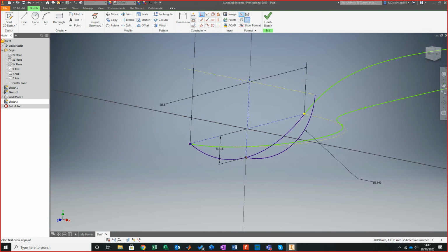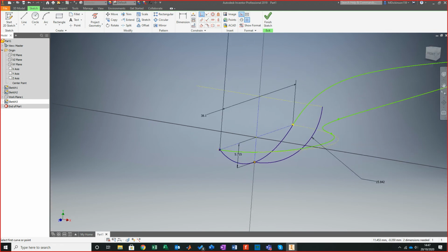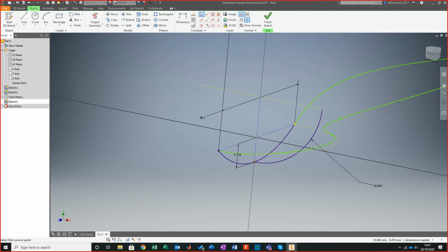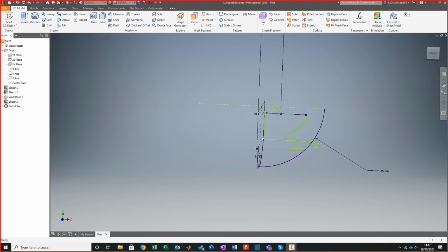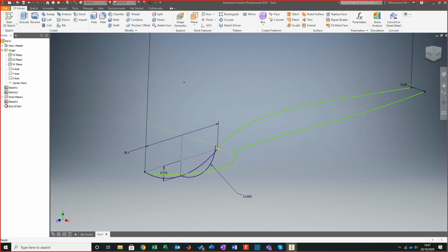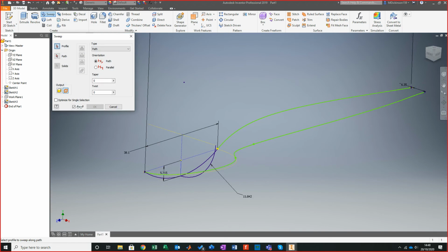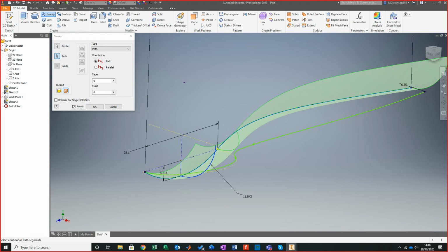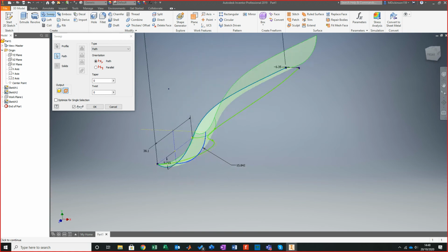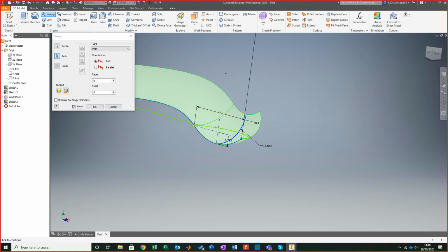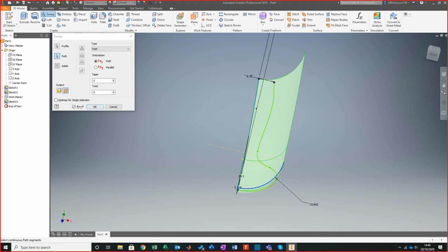So right, we've now got our sketches pretty much nailed. Now it's just fine tuning, it's changing, looking at what's happening. So I'm going to click end of sketch, and let's start bringing some of these together. So let's do a sweep. Now with my sweep, I'm going to choose this. Well, I could do two ways. I could either do this as my profile and this as my path. I know it looks a little bit not like a spoon at this point, but it's going to give me my first overall shape. So I'll click OK.